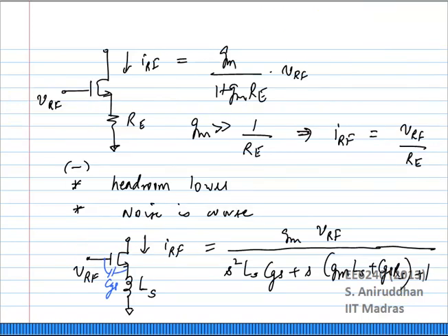You can also improve the transconductance of this common source transistor by adding, for example, a resistive degeneration. Obviously the problems with resistive degeneration are that you need to devote a portion of the DC headroom for this resistance. This resistor produces noise, so the noise figure of the mixer gets worse. But apart from that, linearity will look quite good.